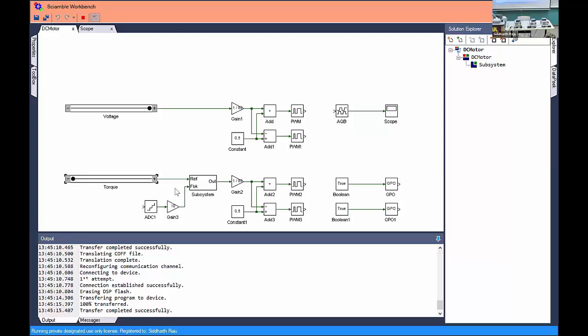And if the current increased, this current flows through some coil, which has some resistance, some inductance. And when it flows through the resistance, it's going to drop some voltage. So the available voltage is reduced. And we already saw when the voltage is lesser, what would happen? The speed will have to come down. All right, so that's what's happening there.